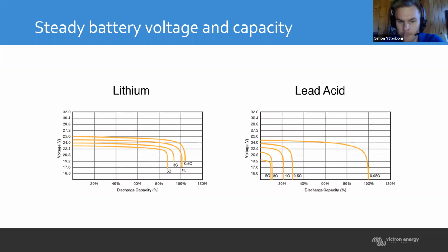So if you are discharging your batteries, here's where you can see if we choose too small of a battery bank, if it's lead acid, especially for our system, we're going to discharge the batteries very fast, and we're going to run through the cycles of this battery very fast and subsequently replace them quite frequently.